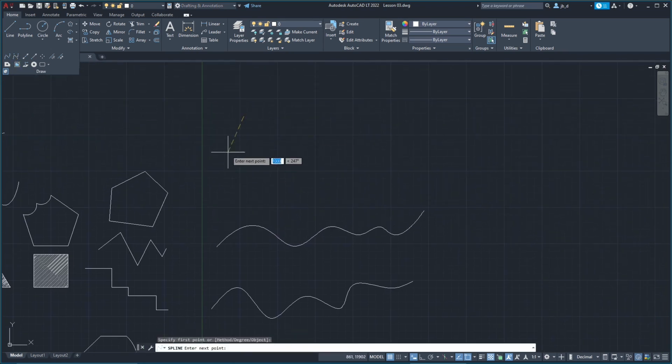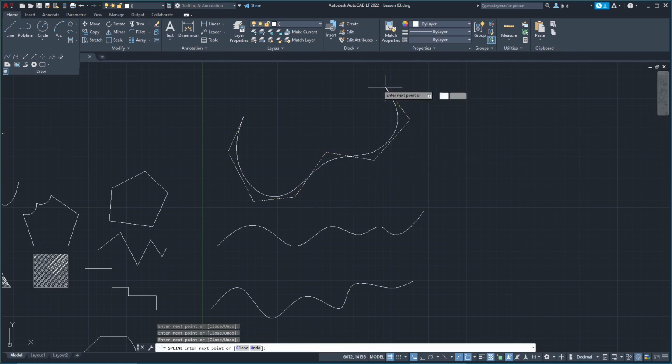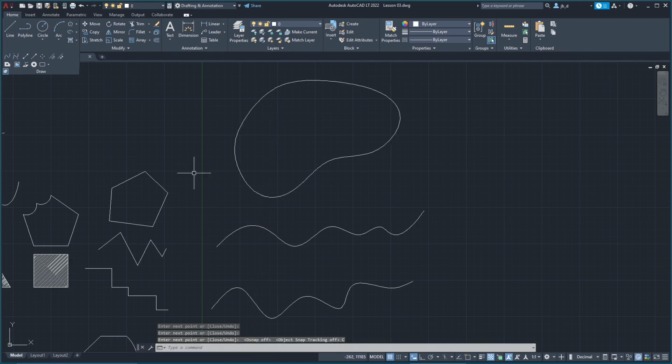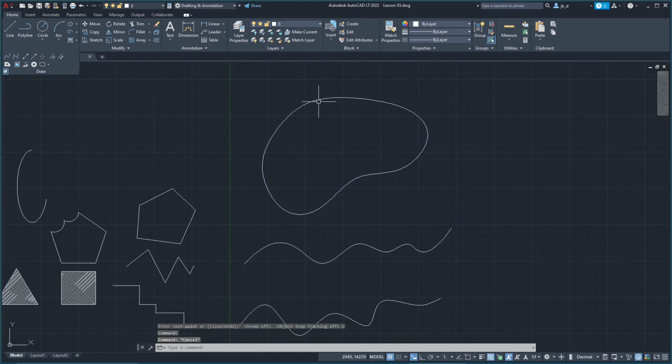And now I'm gonna create a nice closed spline. Now when you're near the closing point, you can either click there and close. Now remember that all those green highlights, like this end point here, those are snaps. So if I turn off the switch down here of the snaps, you won't see them anymore. So it will be more difficult to place that exactly in the endpoint. But sometimes we have here the answer down there. So I can click on close, and there it is. This is the perfectly closed shape, which could become a golf course or a lake.